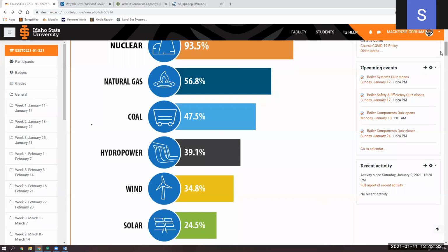Nuclear, it's because they operate at 100% power except for the month-long outage you have every 2 years where we refuel, right? And that's pretty much what nuclear plants try to do. So it's the percentage of time you're at 100% full power, and that capacity factor can be lowered by operating at lower power or by being shut down.